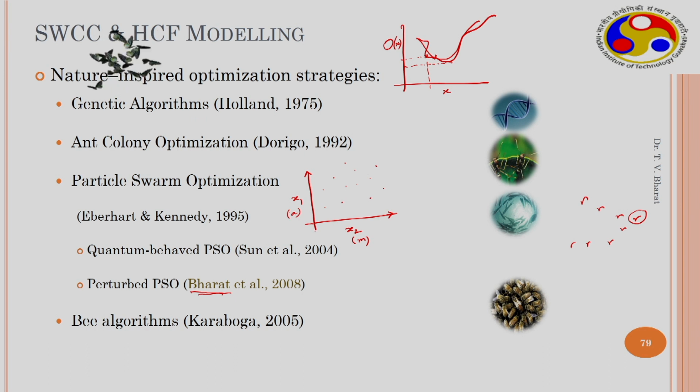We know the limits of this search space as well, because A can vary only within some particular range, say from a minimum of 1 kilopascal to a very large value like 5000 or 10,000 kilopascal, because this is related to the air entry value. And M or N can also be restricted to a given range.